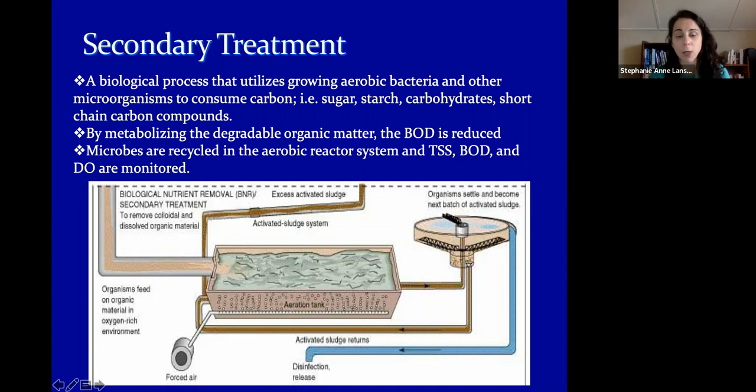And then these microbes are actually recycled in this process. And again, we monitor the total suspended solids, our BOD and our DO. Any additional sludge can be removed, while some of it is actually rotated to get our microbes back in.